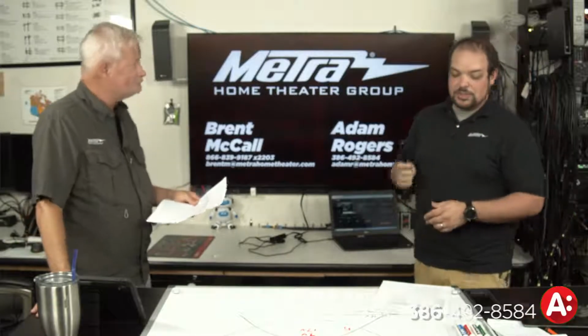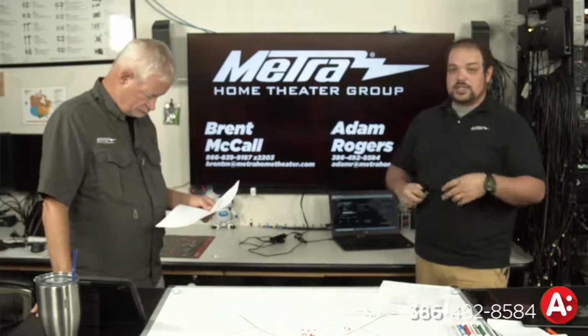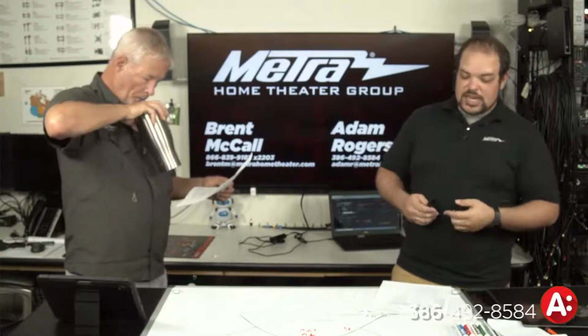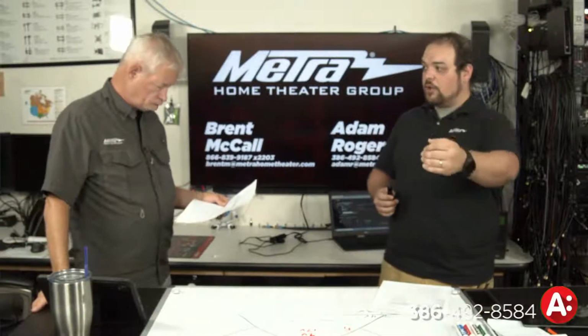That is the standard for what's colloquially known as PoE Plus. PoE Plus is interesting because it still only requires 2 twisted pair, and it does it the same way as the alternative B. It's just a bigger power supply. So now with 802.3 AT, PoE Plus, it supplies up to 25.5 watts at the powered device.